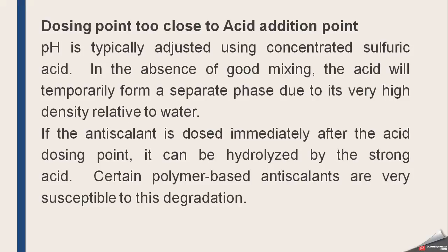So in short, if the antiscalant is dosed immediately after the acid dosing point, it can be hydrolyzed by the strong acid. Certain polymer-based antiscalants are very susceptible to this degradation, that is, the polymer or main backbone of the antiscalant will be degraded.